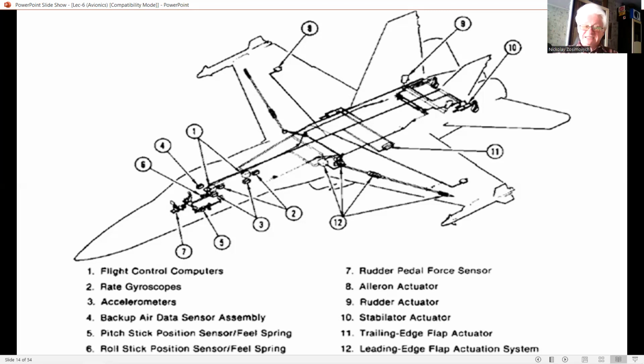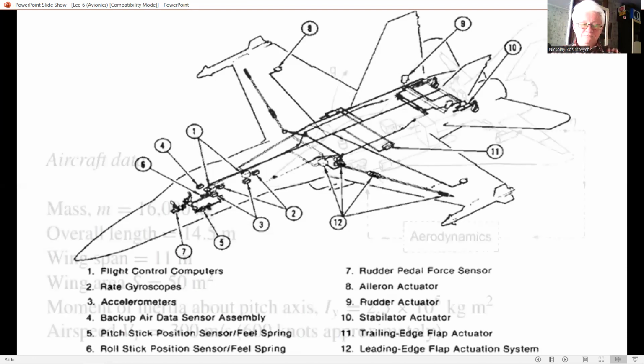Inertially induced excitation forces are predominant at low airspeed in the case of all moving control surfaces such as the tailplane. The aerodynamic excitation forces are large and dominant at high airspeed in the case of relatively lightweight, but aerodynamically powerful wing trailing edge control surfaces such as ailerons, and can excite the wing structural motion.